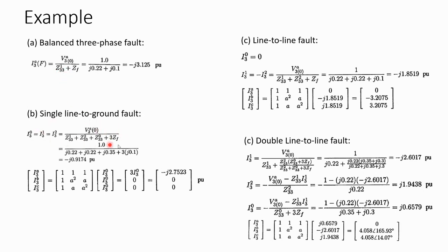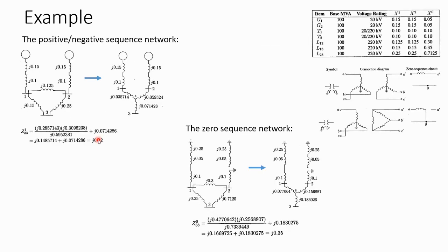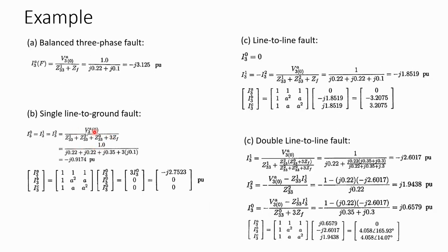And these are the equations that we have derived for the single line to ground fault. And then you can go ahead and substitute the impedance for the positive, negative, zero sequence. And this is the fault impedance. And these three values we have derived over here. And you can substitute there and then determine what is the value for I30, 1, and 2. And then you can determine the phase current through the phase and symmetrical current relationship.